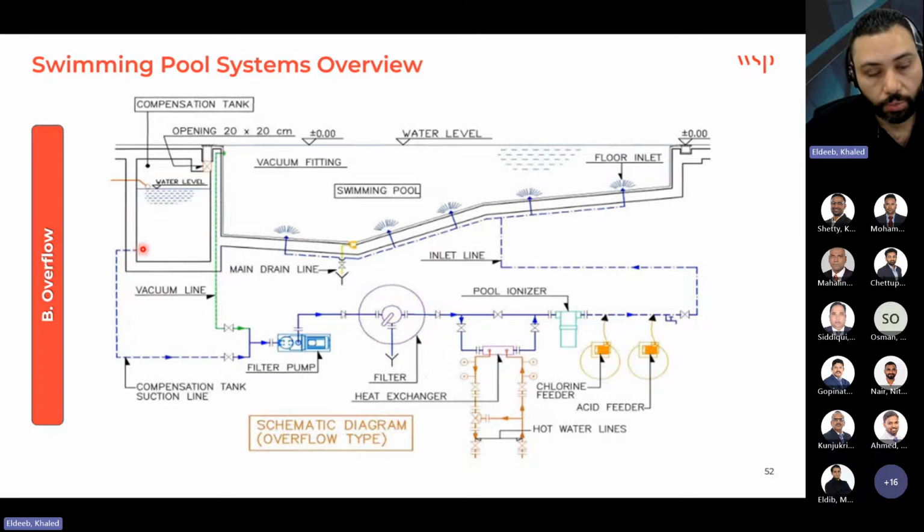You can treat it like a regular domestic water tank, like what we are doing in our project. So we have an inlet coming from the pool. We have makeup water that has to be provided. That's why some people call it a makeup tank, or balancing tank. And we have the drain connection going here, or it could go outside to the drainage network. We also need to consider some space for the displacement water coming from the pool. We'll show you the calculation and details of this to understand how it works.